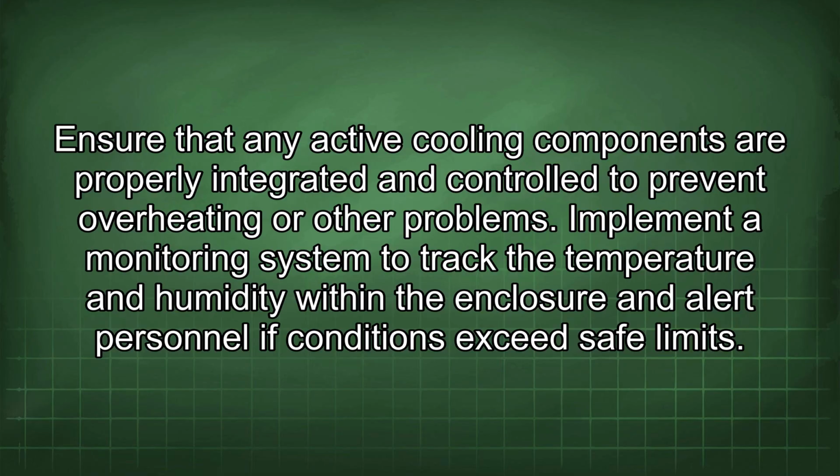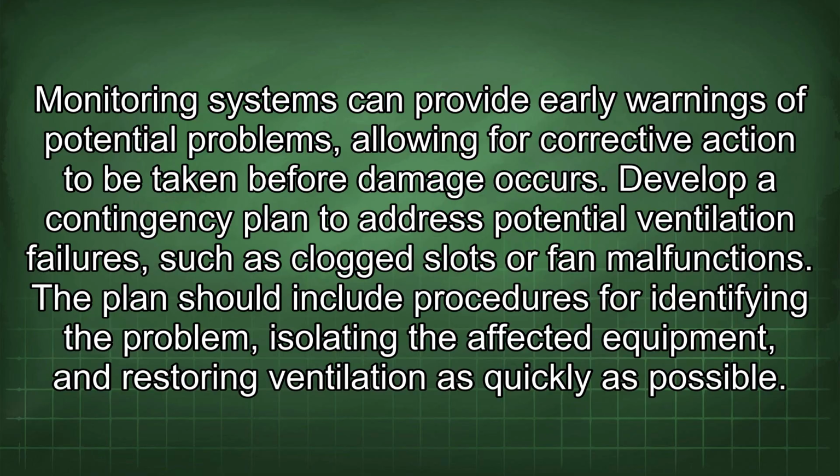Implement a monitoring system to track the temperature and humidity within the enclosure and alert personnel if conditions exceed safe limits. Monitoring systems can provide early warnings of potential problems, allowing for corrective action to be taken before damage occurs.